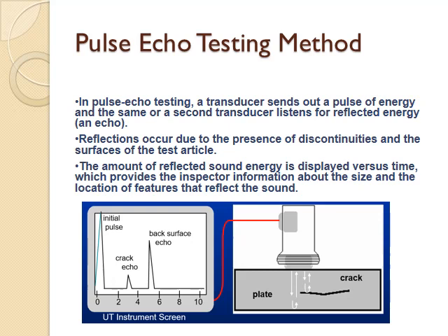But first let us see the construction. It consists of a piezoelectric transducer coupled to the upper surface of the specimen without any air gap between the specimen and the transducer. The pulse generator is connected to the transducer to produce ultrasonics, and the same is also connected to the CRO in order to record the transmitted pulse as shown here.